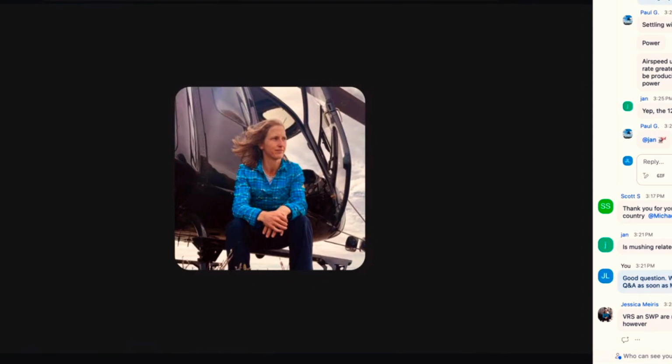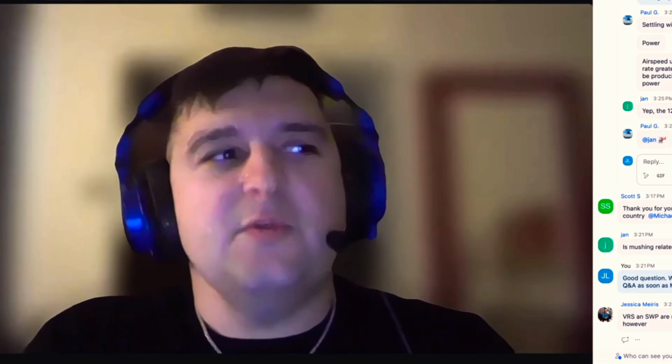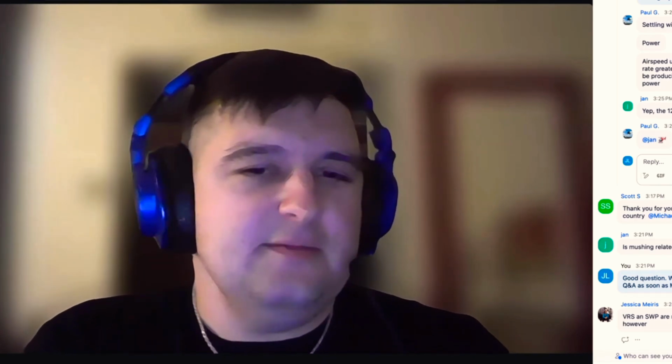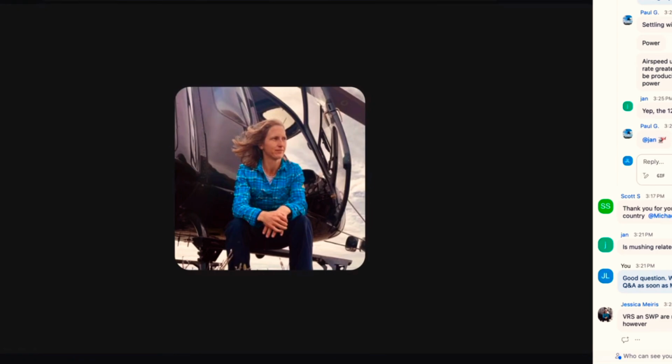Likewise. Will you elaborate though on the differences in VRS and SWP? Yeah, VRS is strictly an aerodynamic condition that's created when a helicopter settles into its own downwash, and settling with power is a result of power mismanagement. So they're pretty distinct. VRS is an aerodynamic thing, and settling with power is more of a judgment and decision-making thing. Okay, so one kind of leads to the other, or could, I should say. Yeah, it could, but not necessarily.